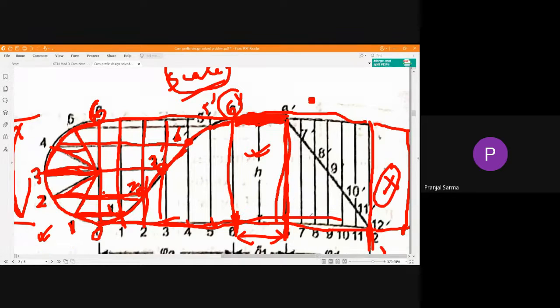After that, we have got descent. For the descent stroke, once again you divide it into equally spaced, even number of divisions. You can go for 6, 8, etc. That's up to you. So we have made 6 divisions. All those vertical lines you have to draw. Sorry, drawing diagrams here on the laptop is difficult. And do the division names, 7, 8, 9, etc. up to 12. And is this with SHM or something else?